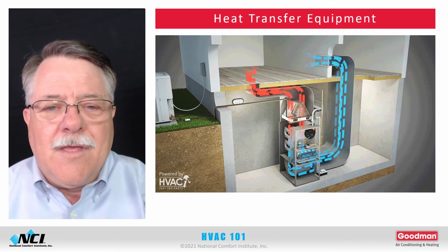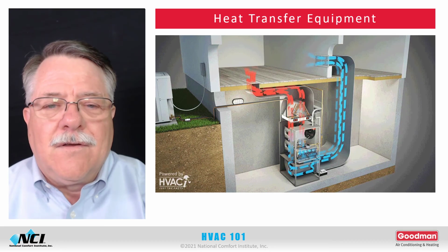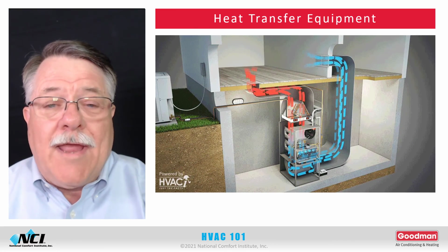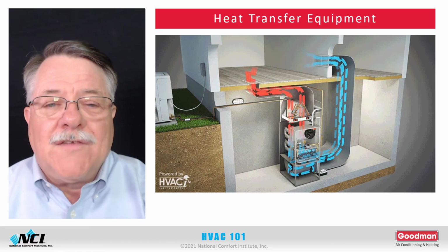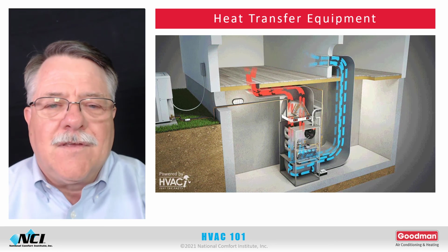If you have a gas furnace, basically the gas furnace takes cool air in through the return system, pulls it in through the blower, runs it up through a heated metal surface known as a heat exchanger. It's heated up by gas burners within the system. The cool blue air is drawn up through the fan, blown across the hot heat exchanger, picks up heat from the heat exchanger surface and then is distributed through the supply duct system into the space.